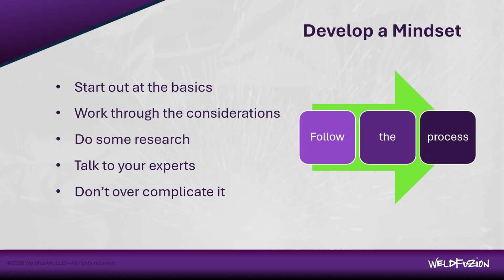If you start with quality requirements, work through the considerations, and talk to the people who actually weld and have experience, you'll make good decisions. You have to consider all those factors. There's no one source that's any better than another. If you jump straight forward into a process or a chart, you'll miss the real world constraints. If your solution requires TIG welding with a 3/8 plate outdoors in January, you might have overcomplicated it.